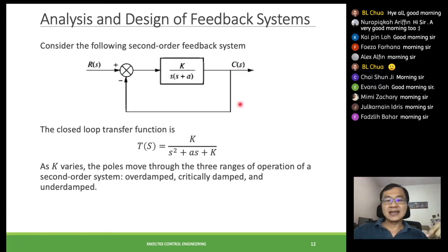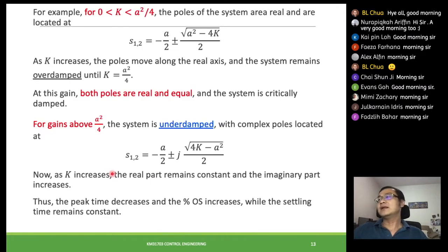Okay, so this is the way where later on we can always control the equations by maybe adding a feedback, right? By adding this to these equations, we get this type of performance. Then from there onwards you can also vary the K, right? By varying the K, the poles we can now shift to different directions by controlling this value of K. Then we can detect the type of system that we would want, and from there also we can select the type of performance that we want, right? So this is the idea behind it.